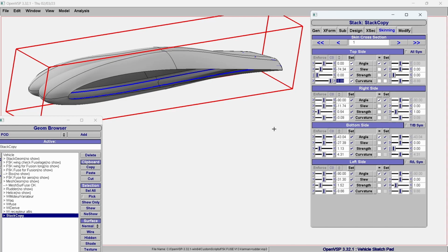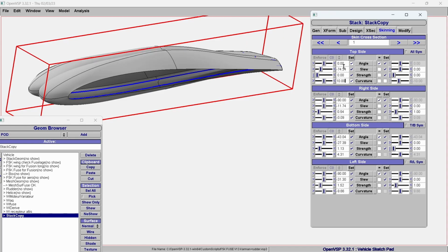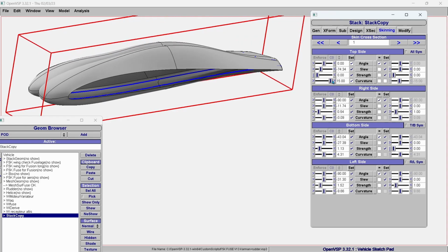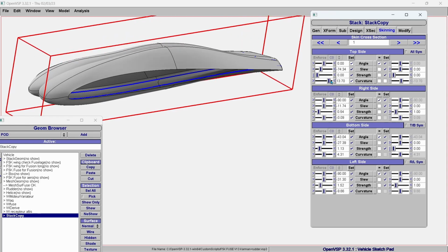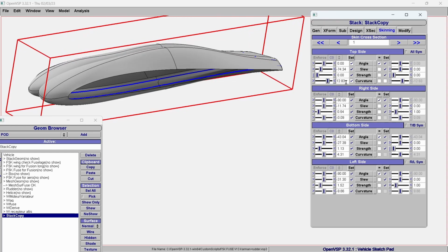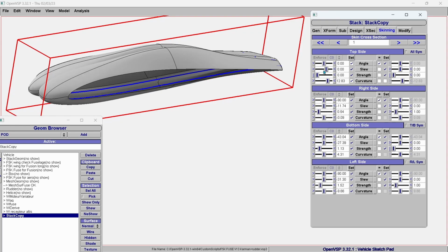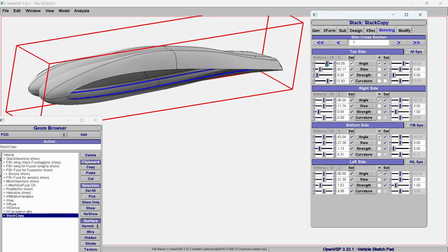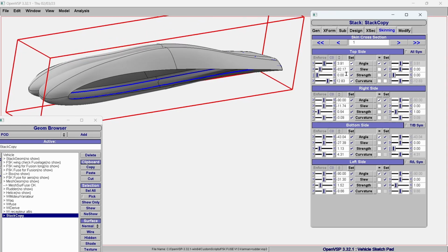If you are not happy with what you see, you can put your value in by hand, because maybe this linear tab is not enough. So we can see that this one is better than what I did before. Maybe you can play with this one and you can play with the angle. Okay, so that was only for the extruder.